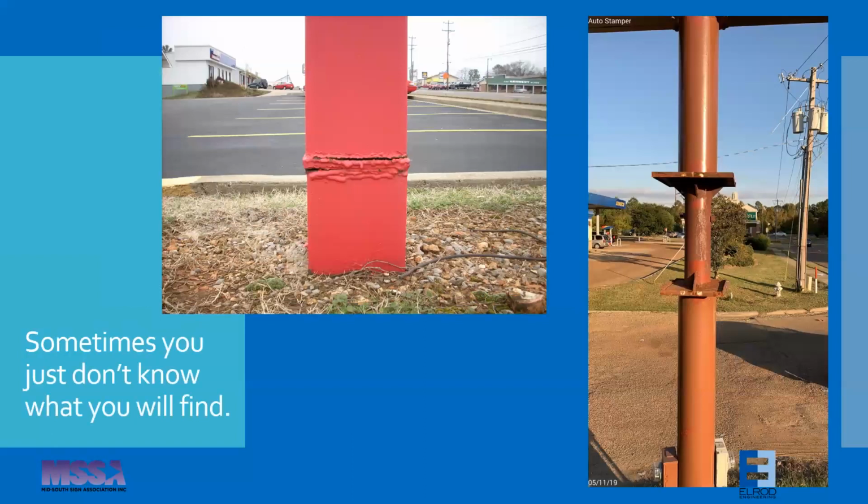Sometimes you just don't know what you'll find. That photograph on the left, I was actually at an adjacent site doing an inspection, and I turned around and saw that. And I honestly don't know what's going on. It almost looks like there's a spiral cut where they tried to stick something in between 2 sections of the pipe, and the weld is almost completely broken all the way around. Fortunately, a few years after this picture was taken, they tore that site down, and that's not a problem anymore.